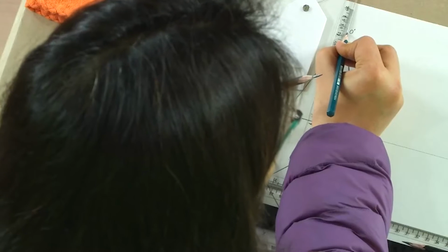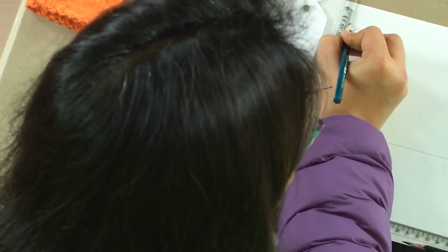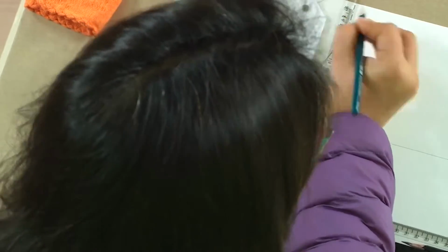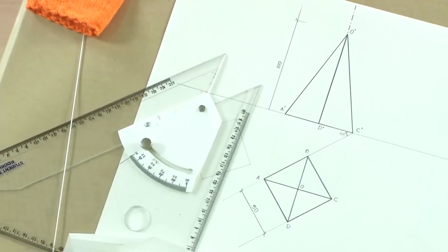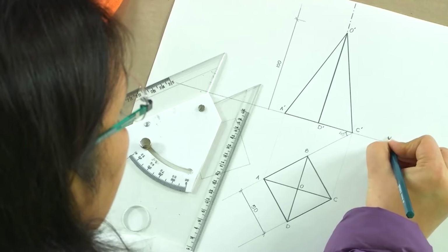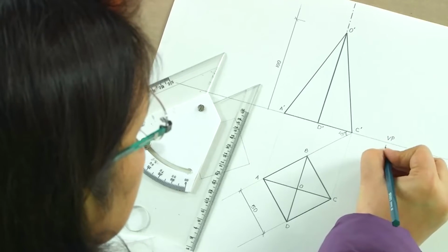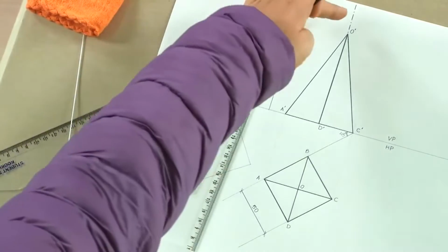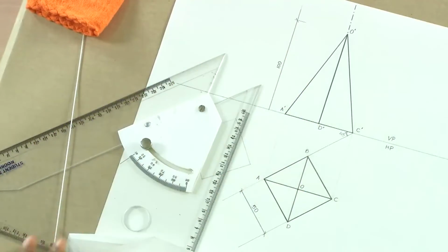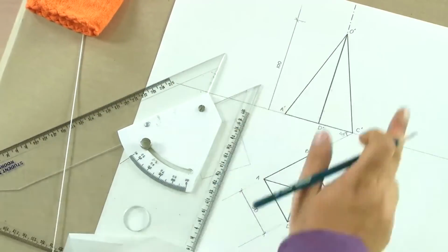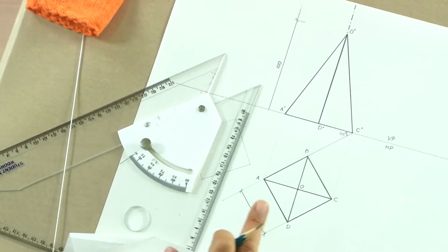That's the condition. Now, one thing which is left for us to draw is the extension of the x-axis line. So, the axis is going to be seen like this, since we will not be seeing the axis anywhere but in the front elevation in VP. This is VP here and this is HP. So, what you see here is this axis which is seen as perpendicular to HP and parallel to VP, which is why we see the true height in VP and the true dimension of the base in HP. So, this is one of the conditions which we have.